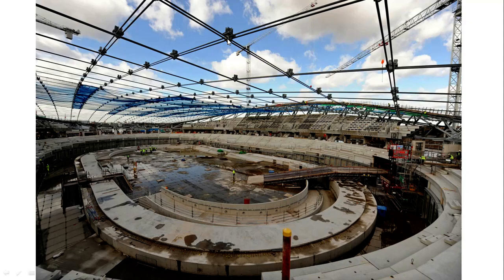And here are the nodes that connect, once they've put everything into tension, all the grid connected at these points. Remember again the importance of these little nodes. Now these nodes are not only connecting the wires traveling in two directions, and again we've got this principle of doubling, not one big one but two small ones do the job, and they're lighter. These also allow what's known as the cassettes, which is the actual roof covering, to be connected on top of the wire. The wire is very rigid.